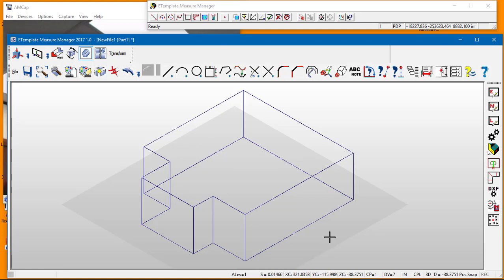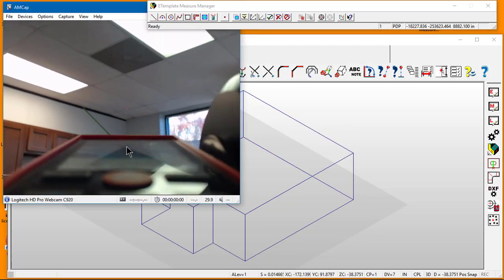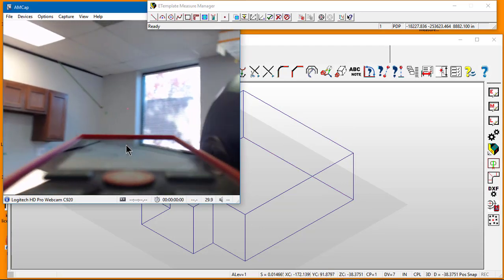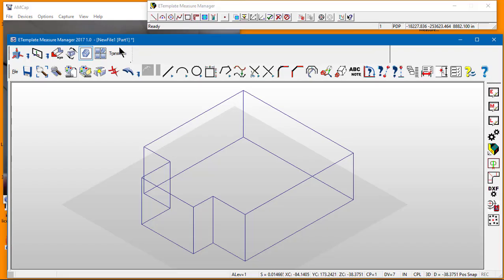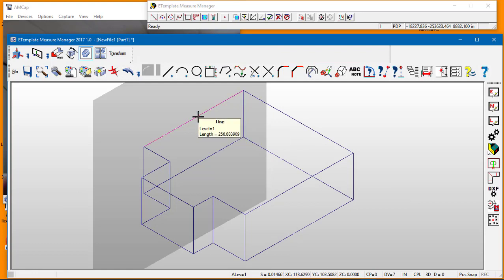So now we're going to go on to working on the wall sections to add the windows in. I'm going to begin on these walls. So in order to select that wall, I'm going to go to my plane selection tool. I'm going to select two adjoining angles. And that would become my working wall, although I wanted to make this my working plane. So I'm going to select that again. I'm going to select this and this. It becomes my working plane.